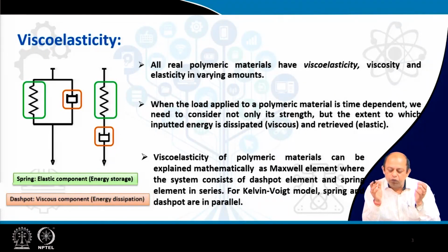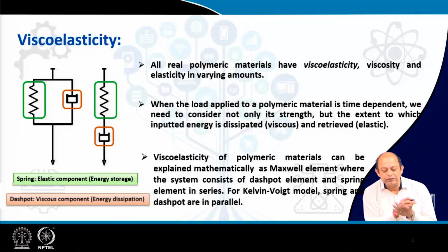So, when a load is applied to a polymer sample in a time dependent manner, we need to consider not only the strength. Strength is a very transient experiment where we do not take time into consideration at all in most cases, but to which extent the input energy is dissipated or how much you retrieve, and that is what actually a viscoelastic experiment does.